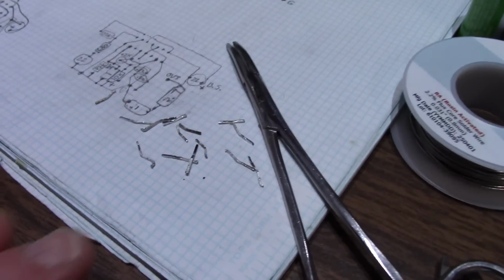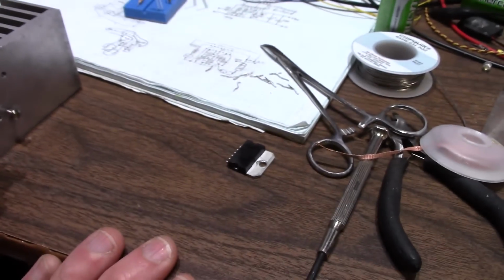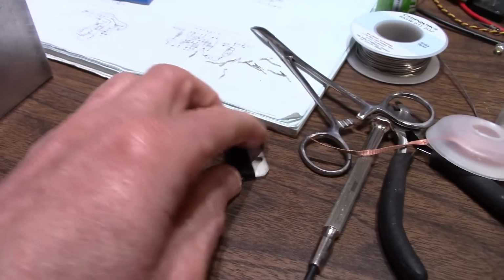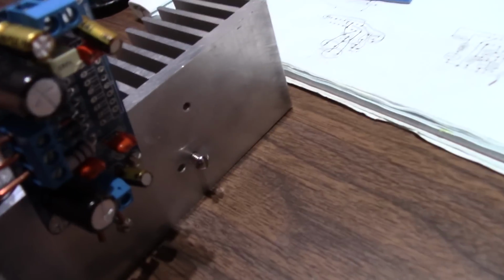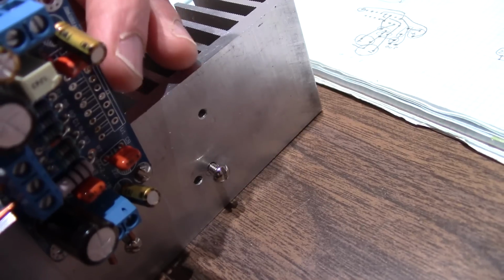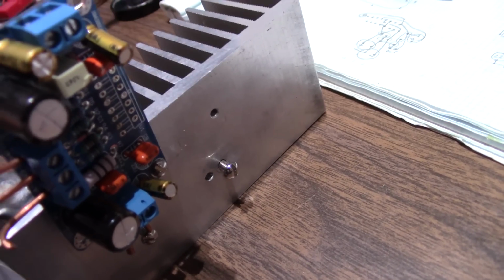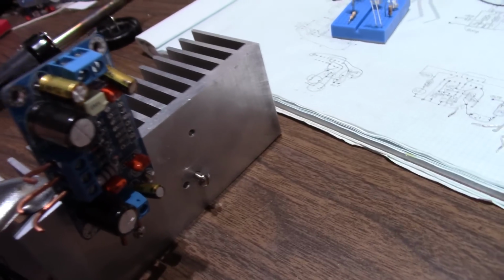So I had to take the pins out individually. I don't have the tools or the technique to get a whole chip out at once on these double-sided boards. Okay, so now I'll have to clean those holes out. I'll probably have to add solder on there and then resuck it back out. Hopefully it clears them out, or stick a piece of wire through it and heat it up.